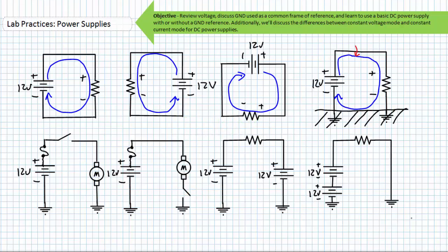Let's reopen our switches for both a high side and low side switching arrangement and insert an additional element in series with our switch and motor. In this case, these are both fuses. I know we haven't gone over the details of fuses yet, and we will do so in the very near future. But for right now, understand that a fuse is a circuit protection device. And in the event current flow exceeds the fuse's rating, the fuse simply melts and becomes an open circuit. Now, with this additional fuse element in play, consider the safety aspects of both high side and low side switching.